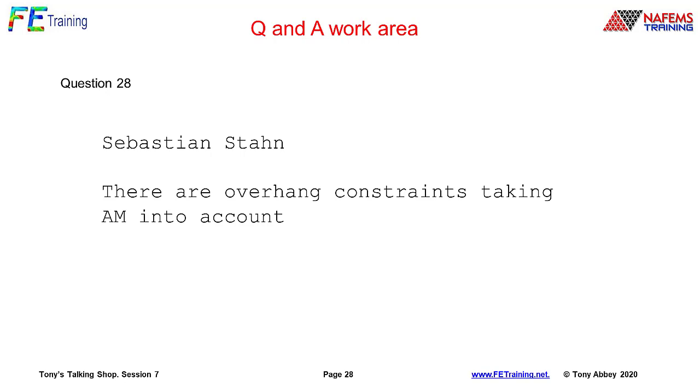I view those at the moment really as kind of band-aids. They're very, very useful, but eventually we're going to get to a stage where each step of the additive manufacturing process is going to have a little FE analysis behind it to say what can we do, what can't we do. So the way we actually evolve the component in the additive manufacturing process, it's a manufacturing process simulation, is happening simultaneously with our structural optimization. So there's early indications of that happening.